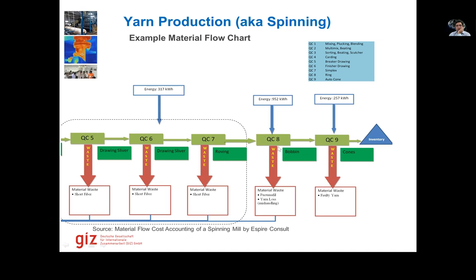Then we go to the process called ring, the real spinning process. Here we have spinning, and we might have twisting, with different kinds of twists. We take the sliver that came in and start twisting it in the machine. When we twist it and stretch it, it starts to become yarn, and this yarn is wrapped around small bobbins, which is a kind of finished yarn.